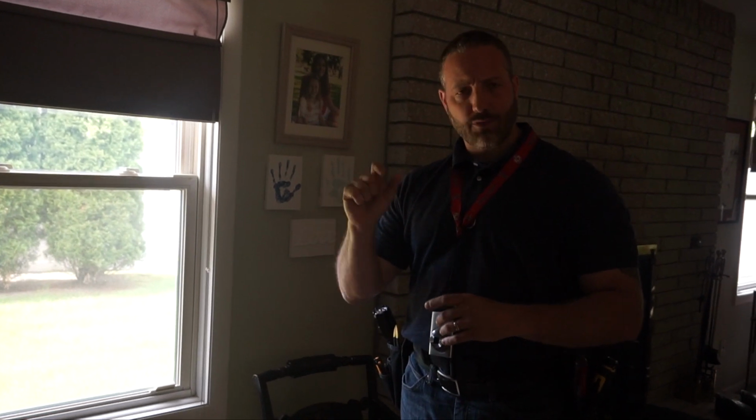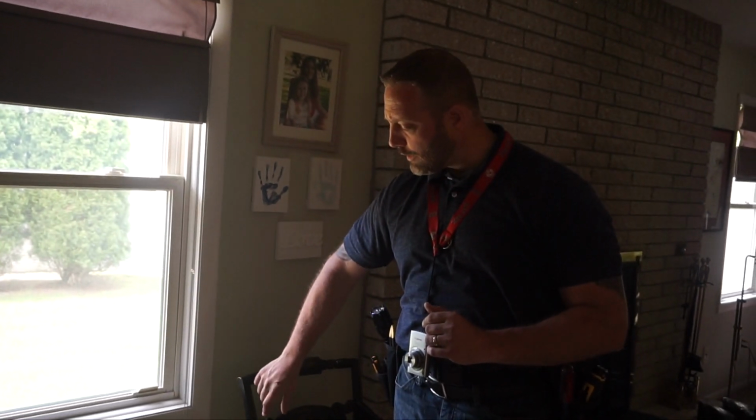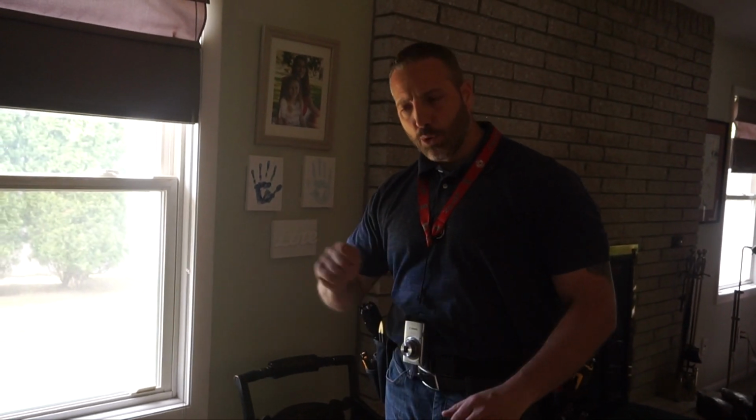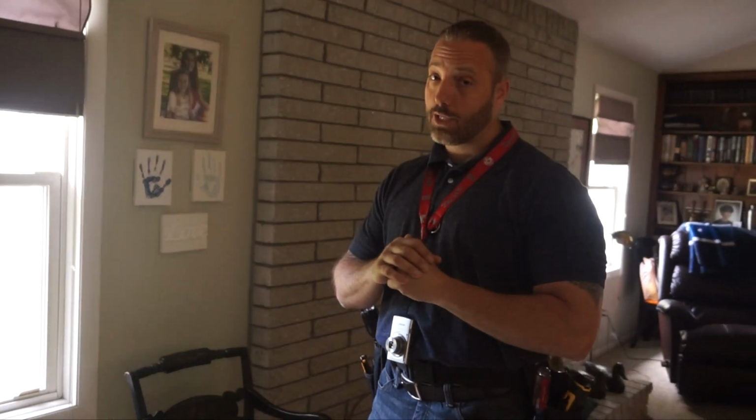Sometimes they'll have those safety plugs inside the outlet. If they're all like that in a room, I do pull them out, I do test it, but make sure you put it back in there, because if you don't, then you could be liable if a child ends up getting injured. Initially, if the sellers have it in there, you've got to put them back because they have it for safety reasons.